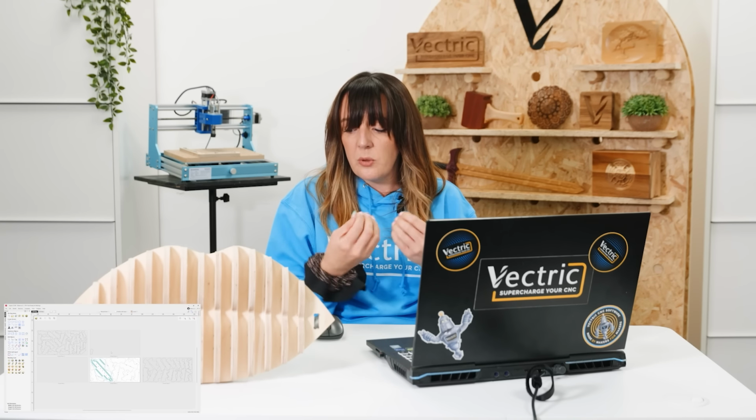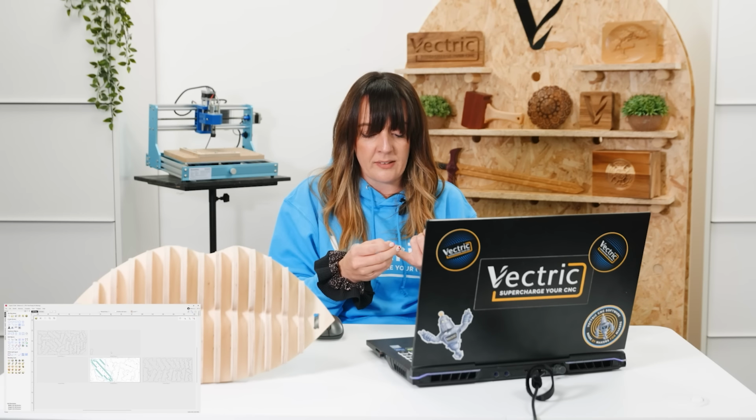Now before we go ahead and think about our toolpaths, as this is a slot together part, I highly recommend that we take an hour, half an hour, to think about test pieces. Okay, so we're going to take advantage of this extra sheet that we've got, and look at applying some tests. So what sort of tests are we talking about? We're talking about tests in order for us to figure out the best allowance for our slots.